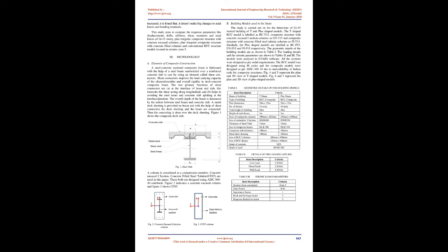2. Literature review. Vamshi Krishna and S.V. Surindar [1] presented a paper showing the comparison of seismic analysis of RCC and composite 18-storey buildings. The results show that some parameters such as time periods and storey displacements were higher in composite, and storey forces, bending moment and shear forces were less in composite structures.